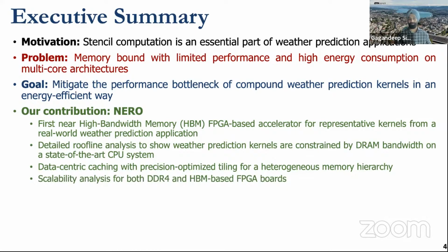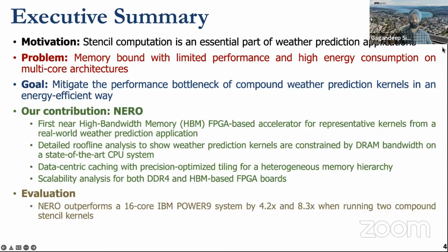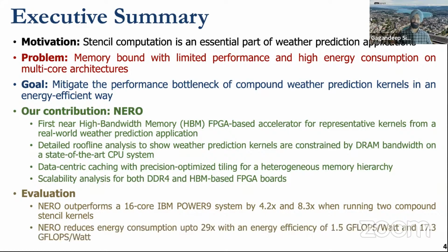We also perform scalability analysis for both DDR4 and HBM-based FPGA boards, and we provide various insights based on that. In our evaluation, we show NERO can outperform a 16-core IBM POWER9 system by 4.2 times and 8.3 times when we are running these two compound stencils.